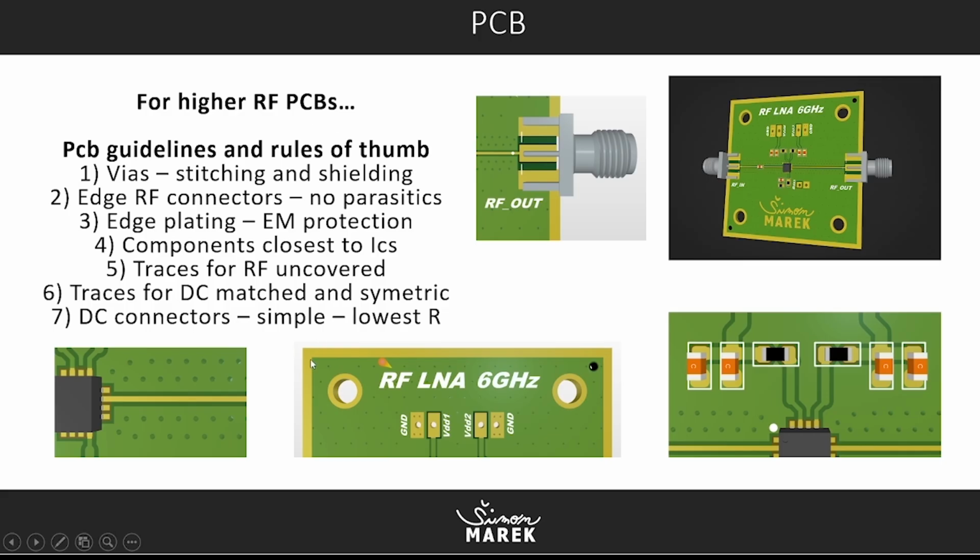Edge plating is this gold frame, which shields the whole circuit and provides connection to the ground, so you can connect it to some chassis, or some kind of aluminum box or whatever.